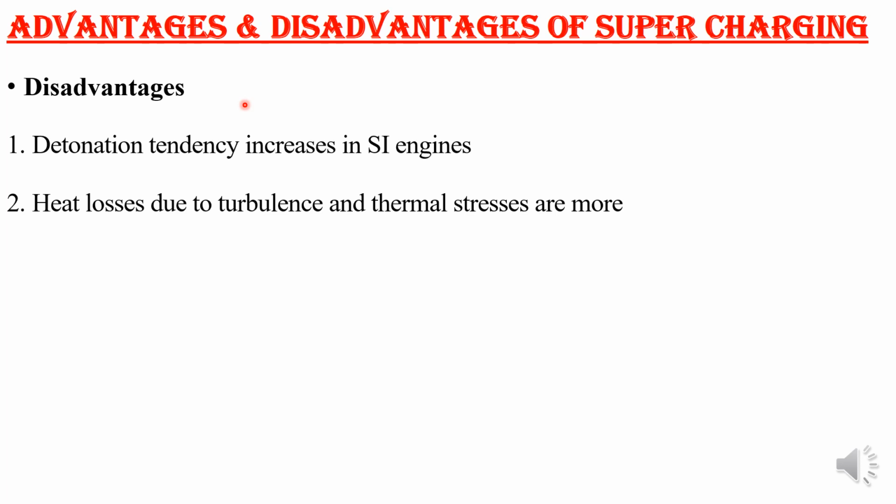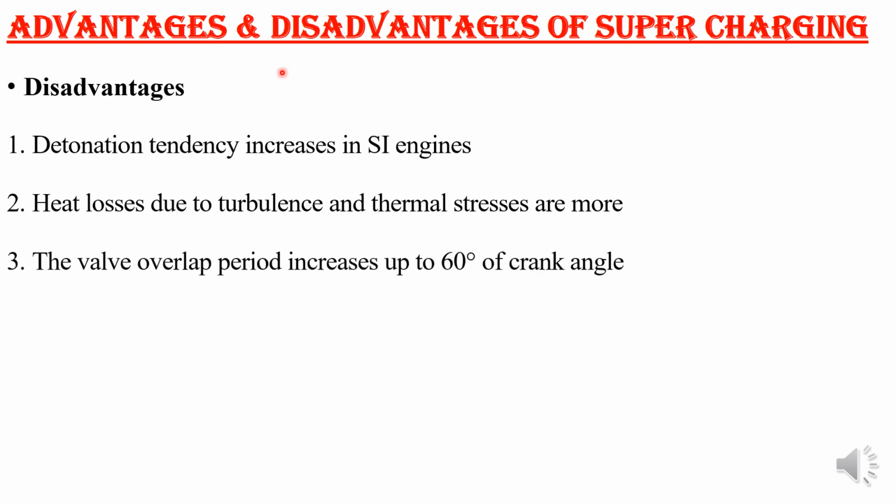Then the third one is the valve overlap period. That is nothing but intake and exhaust. Because of higher pressure, your valve might be designed for atmospheric pressure, so valve overlap period may increase up to a 63-degree angle, which is not a desirable condition, because your charge may go along with the exhaust. That might be a loss of fuel quantity or air quantity along with the exhaust gas, if the valve overlap period is increased. So that might be another disadvantage.